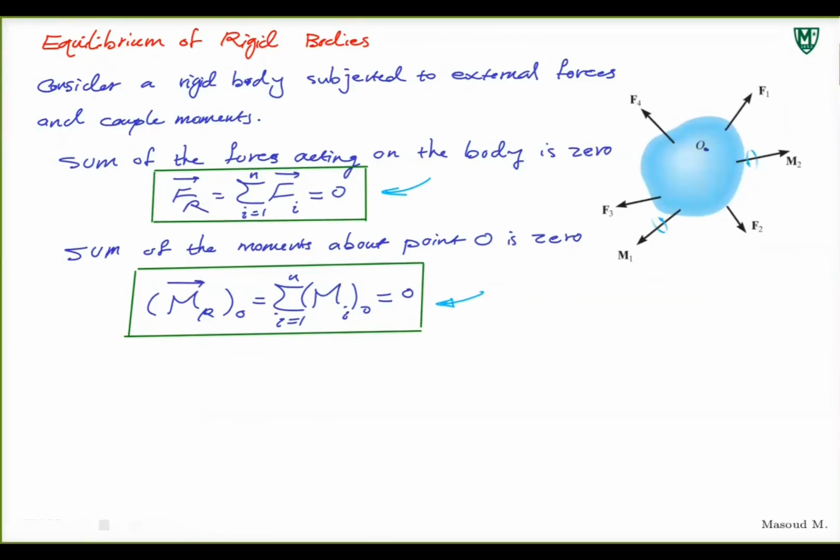All right. So the process is we start from rigid bodies. We draw the free body diagram, the same process we're doing with the particle, right? We isolate the rigid body and draw the free body diagram representing all the forces. Remember those 4 forces we talked about: the spring force, cables and pulleys, which could be ropes or chains, smooth contact, or you can think of it as normal force, and weight.